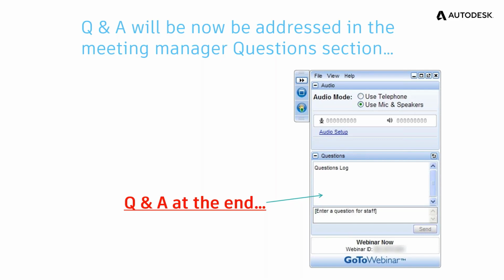Oh, here's a good one, and it bit me a few times years ago. Sometimes when I make a block with visibility options, the triangle used to change them disappears when the block is moved. Why does this happen, and what can I do to prevent it? Be careful when you're selecting your make visible, make invisible.